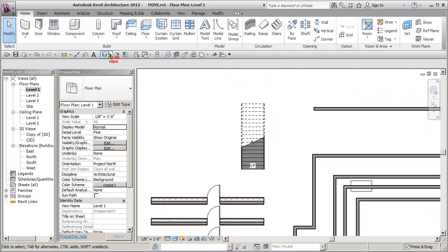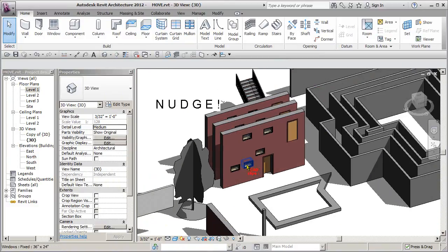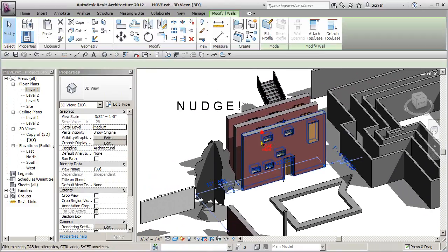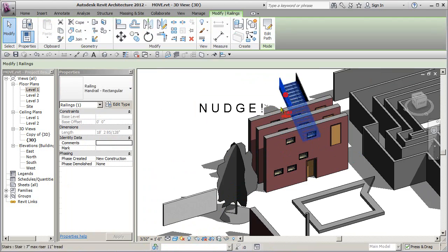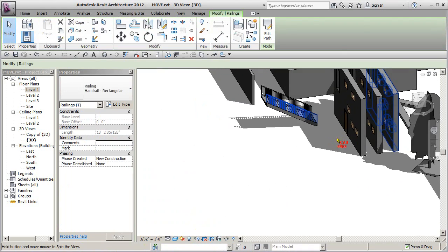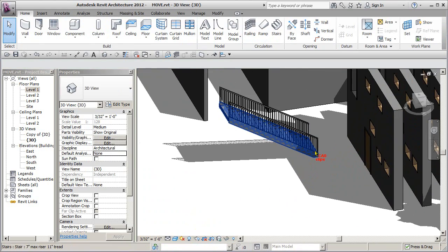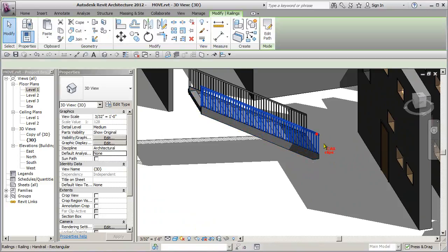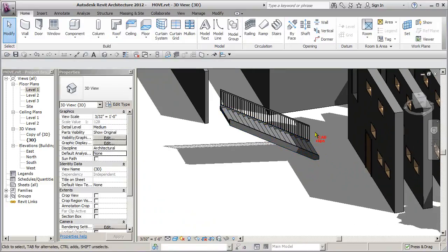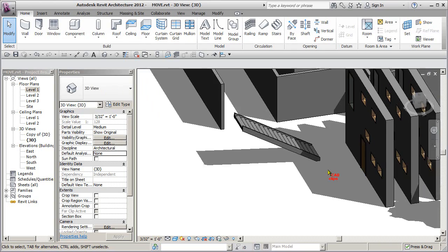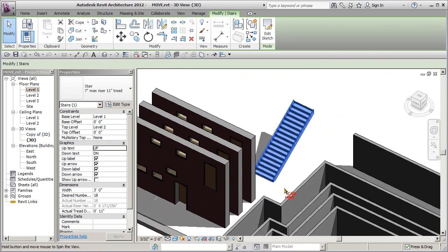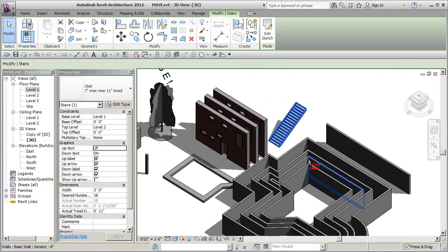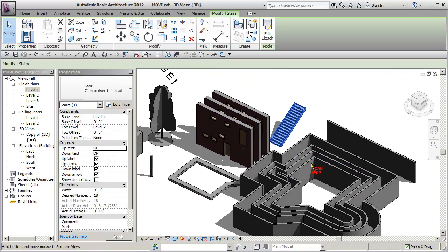Finish that up. Go to my 3D view. Shift middle mouse button. Oh, I've got my view locked. Shift middle mouse button, and there's my stairway. So using the offset tool is a good way to lay out your treads and risers in your stairs. Numerical, and don't forget to turn your copy option on.